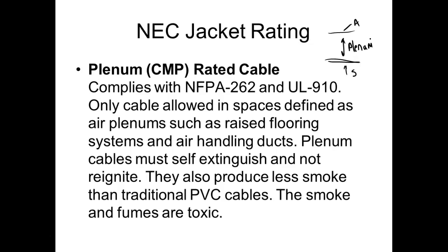When we start burning a lot of these jackets, they put out gases that are very, very dangerous. Also, a lot of insulations will burn a long time. So this one will extinguish real fast, and it produces less smoke and fumes that are not toxic, right?